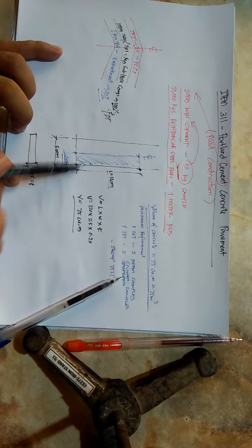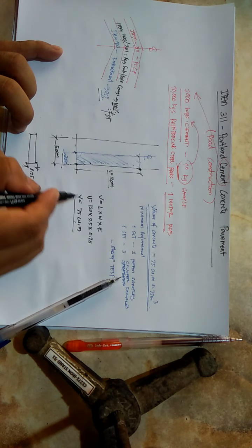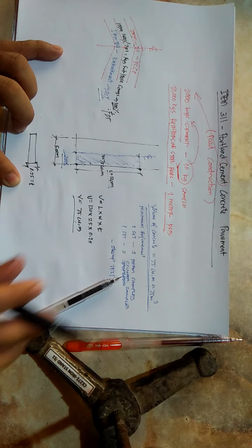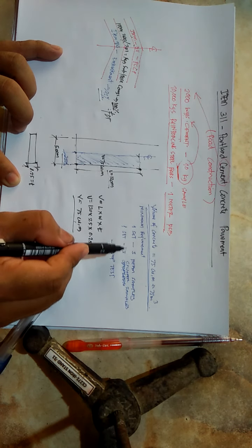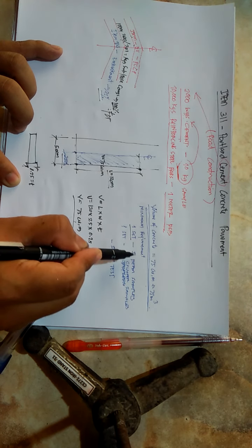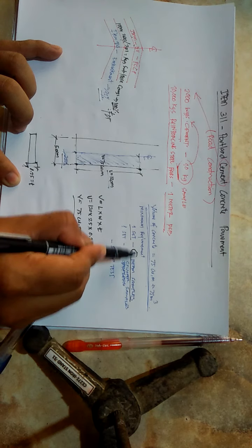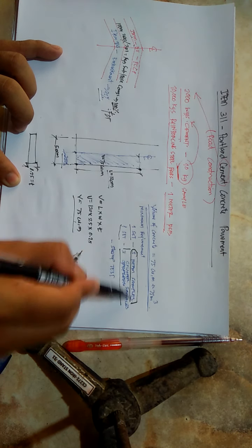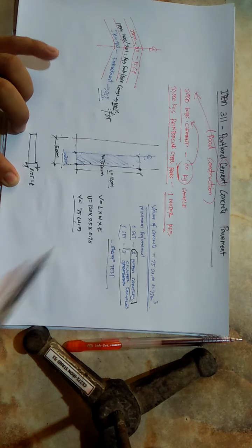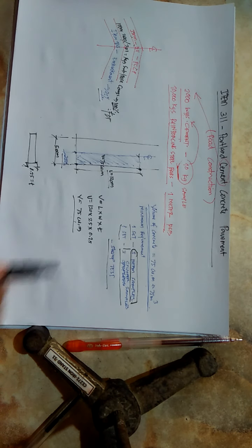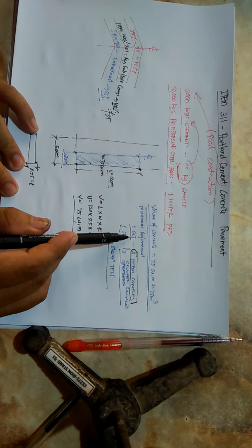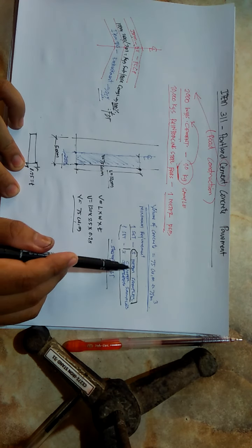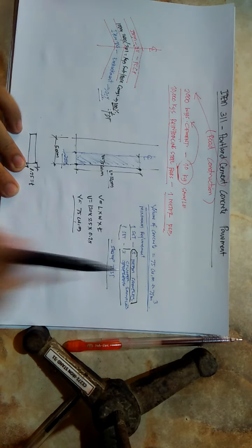Tama? So, exacto. So, meaning to say, itong volume mo dito na 75 cubic meter, the minimum requirement na dapat mong gawin, magawa ka ng isang set composed of 3 beam samples, isang set composed of 3 cylindrical samples, and isang set ng slump test. Okay? So, now, let's start first with your 3 beam samples and 3 cylinder samples.